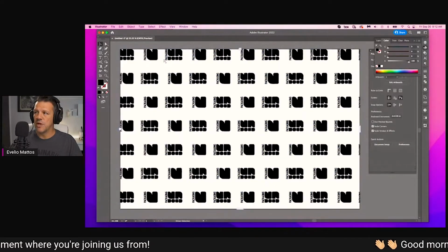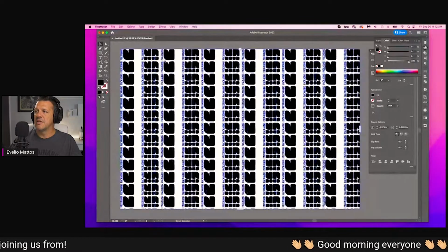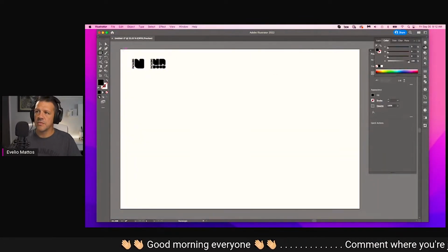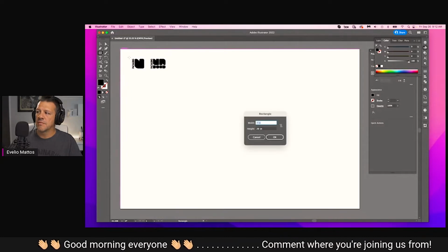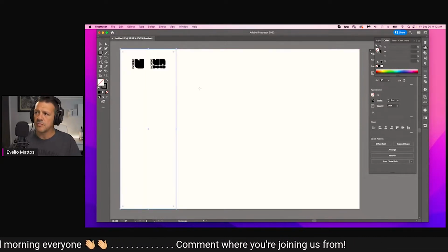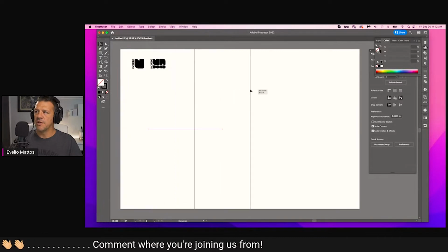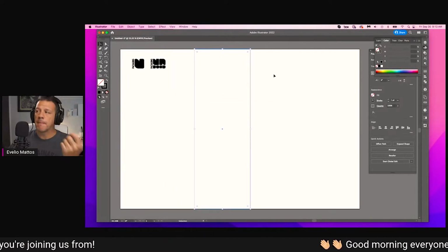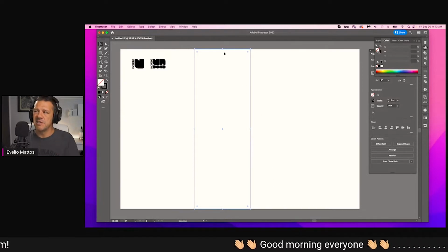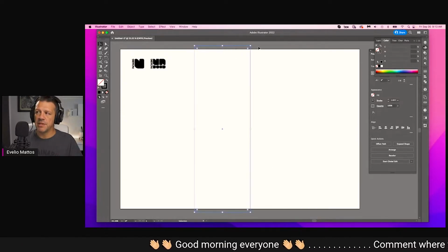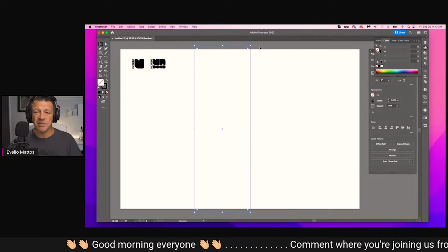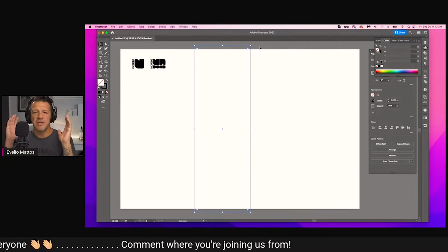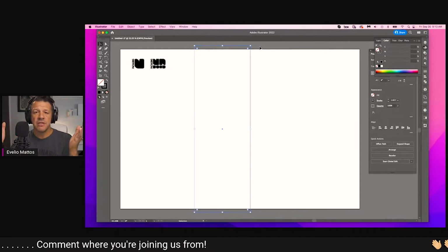So what I prefer to do is start here. If I start with whatever the circumference of the cylinder is, that's my width, then my tissue height. And for tissue, you're probably going to have a little bit of a bleed. It depends on who you're working with. It's never a ton. It's maybe like 1/8 of an inch, max 1/4 of an inch. They're never going to print to the edge of the roll.